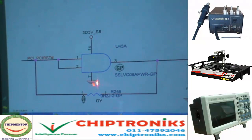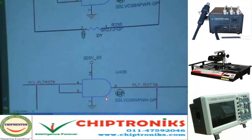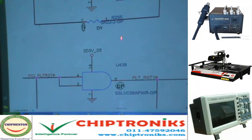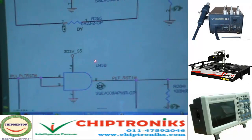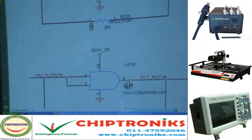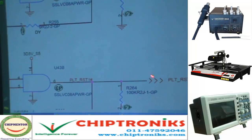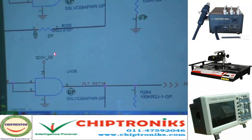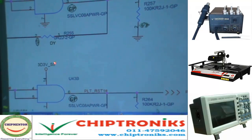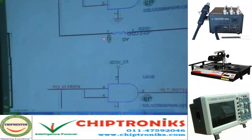U43A is a single IC divided into two parts in the diagram only. See over here, it's the same IC, U43A, U43B. The main purpose of this IC is to make the output of PCI_PCI_RESET and PCI_PLT_RESET 3.3 volt. Fix them at 3.3 volt. This is one 14 pin IC and it's divided into two parts in the diagram only.